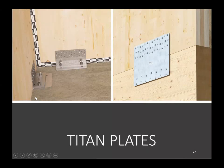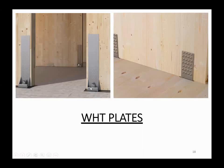Here in this diagram, we can see it's fixed to concrete. We've got a washer and hold down bracket, so a very, very strong connection. We've got a sealing tape, which allows for insertion of some element of waterproofing, air tightness, soundproofing. Once again, WHT brackets.